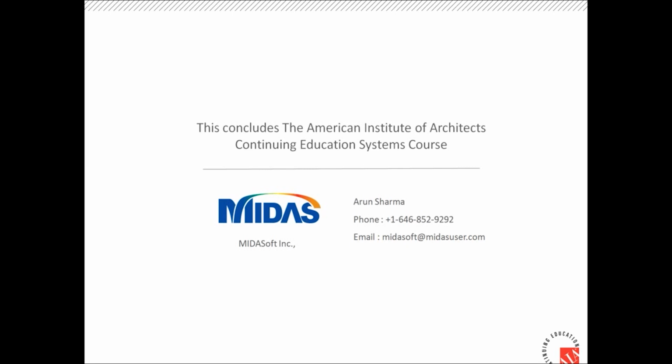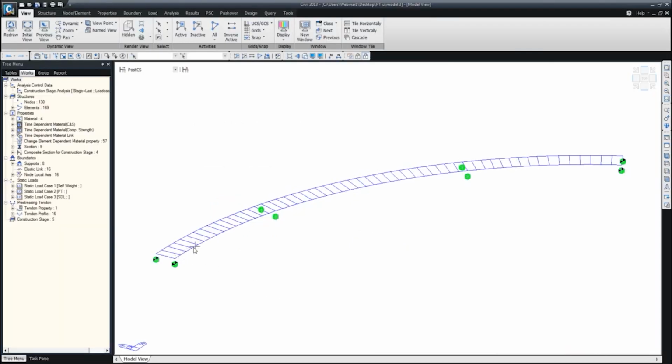What we are doing here is modeling the cross section as a line element with all the stiffness taken in the longitudinal direction, and these dummy beams are the members that are connecting the adjacent girders together to transfer the forces from one member to another.